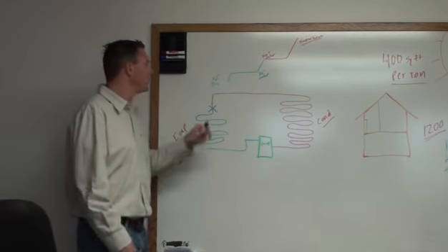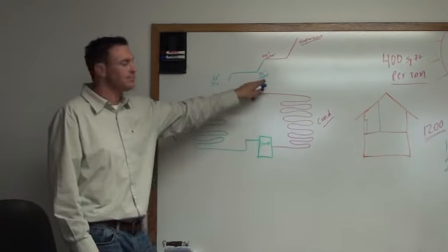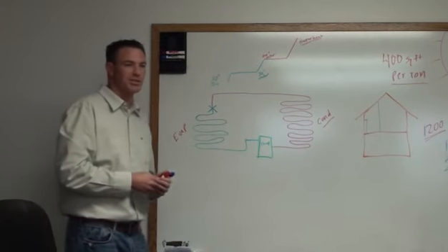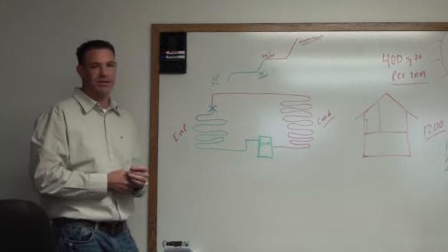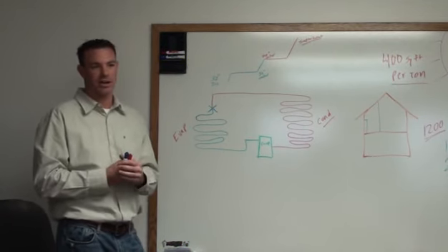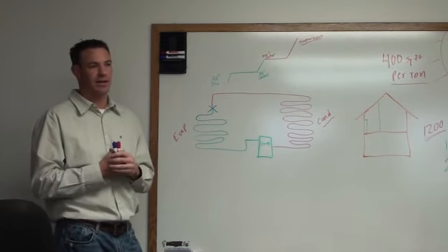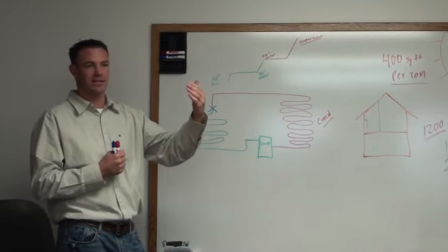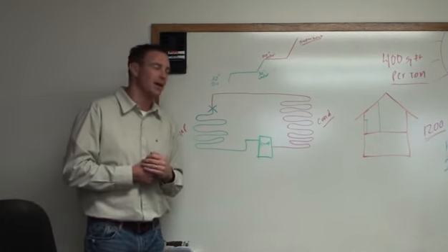Okay? Between point A and point B, we've done something that's called change of state. Between point A and point B, we've done something which is called adding latent heat. Now, so that you guys understand the difference between latent heat and what we normally call sensible heat: sensible heat is heat that makes sense to us. Okay? Temperature change from 32 degrees to 40 degrees, that makes sense. You can read it on a scale, that's called sensible heat.